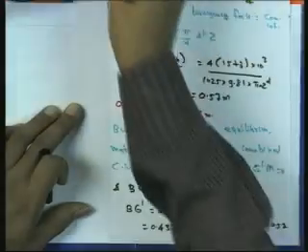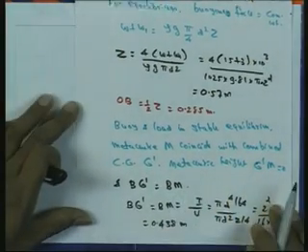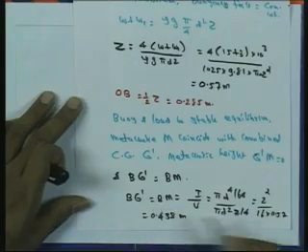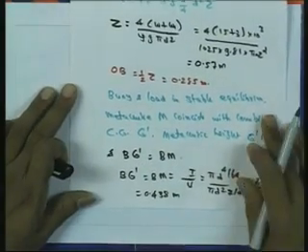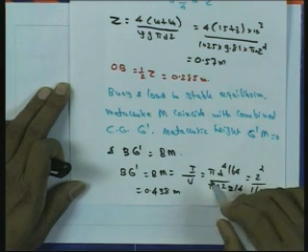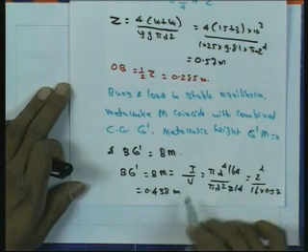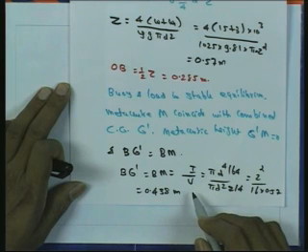That means, since G dash is equal to the metacenter M, BG dash is equal to BM, which as per the formula we have derived is the second moment of the area I divided by V, the volume of the displaced liquid.